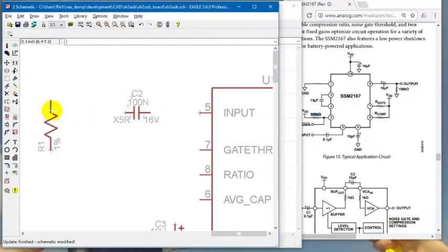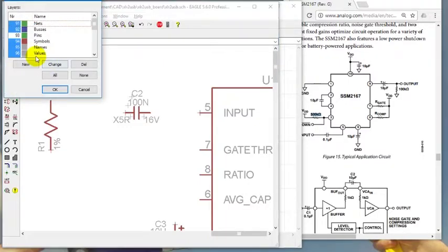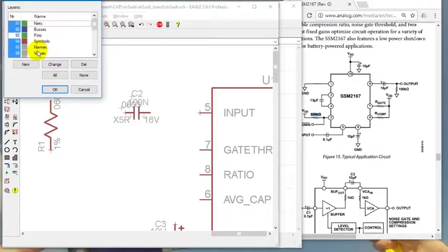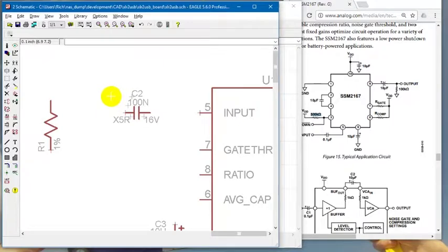Hey, that's what we're looking for, right? Because now I turned off that package layer. Turn it back on. 0603s all around. Okay, good deal. So now I've got this R1 who's hanging out, and he looks stupid because all of his stuff is oriented in strange directions.